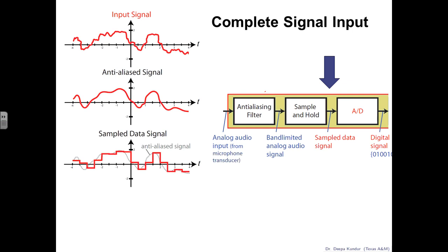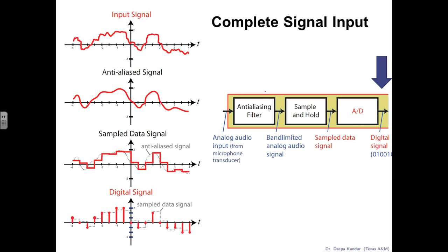This is often necessary to reliably do the analog to digital conversion process because of the way A to D converters work. If you're changing the input, then that may confuse the digitizing process, and it may come up with the wrong value for what level the signal is. Beyond the A to D converter, we have the sampled signal.